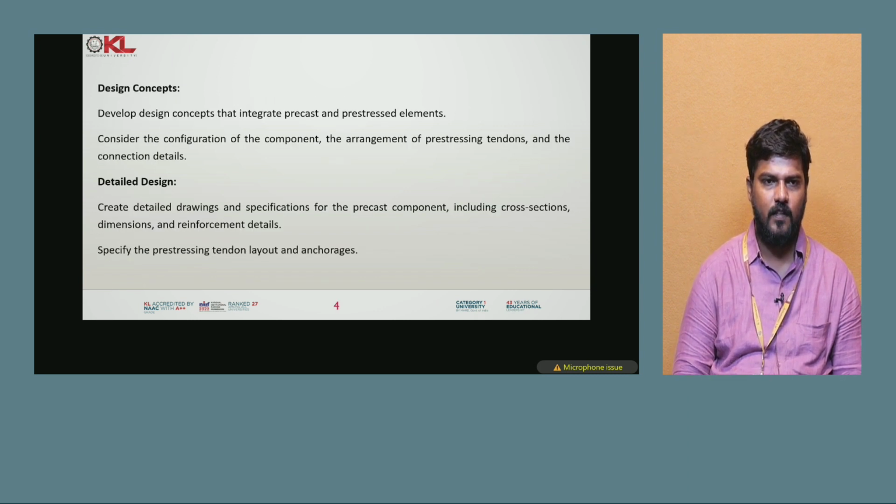And coming to the next one, the design concepts. Develop design concepts that integrate precast and pre-stressed elements, considering the configuration of the component, the arrangement of the pre-stressing tendons and the connection details. And next one is the detailed design. Create detailed drawings and specifications for the precast component including cross-section dimensions and reinforcement details, specifying the pre-stressing tendon layouts and the anchorages.